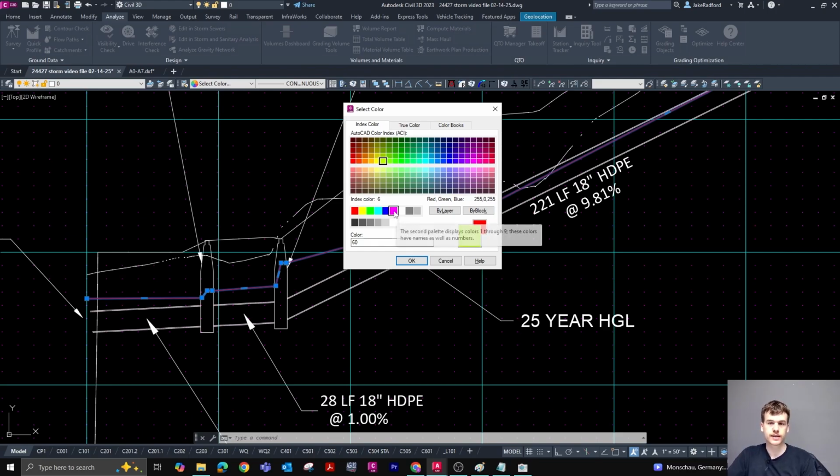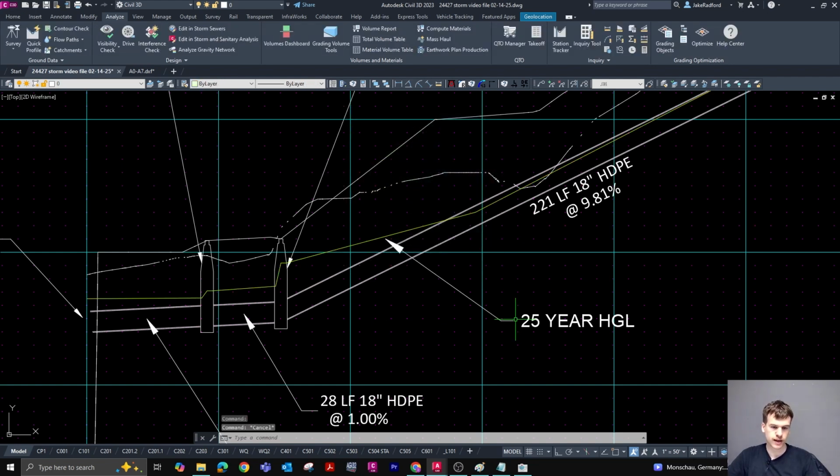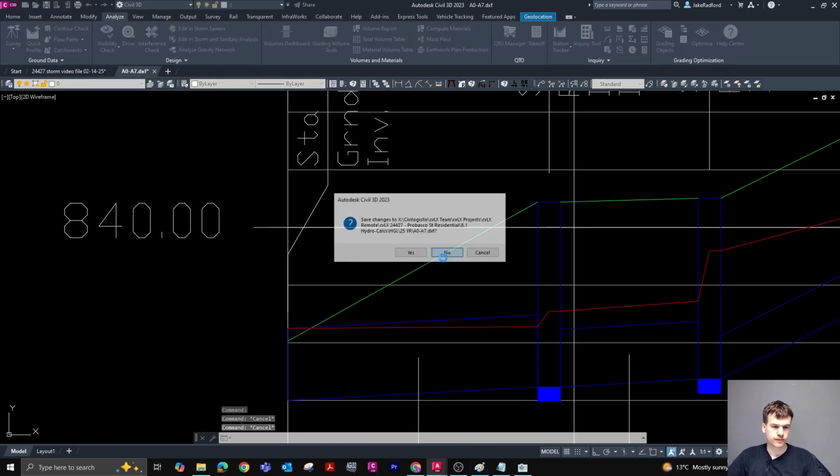Like magenta has a thin line type, but it's very, very light gray. You can hardly see it. But these two colors, 60 and 150, they plot very, very dark, but they're very thin so that when they're right on top of each other, their line thickness doesn't muddle them together. So I'm going to go ahead and select that color for that one, just like that. And then I can close this out. Don't have to save it.